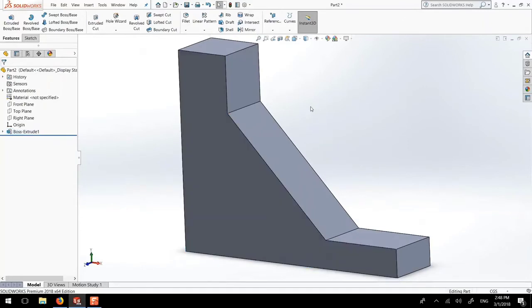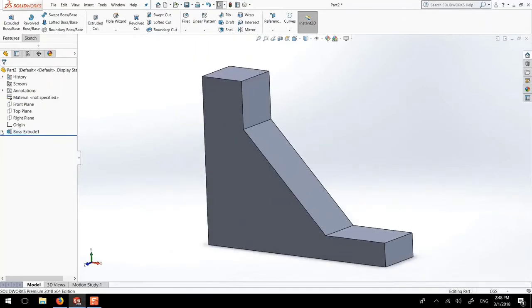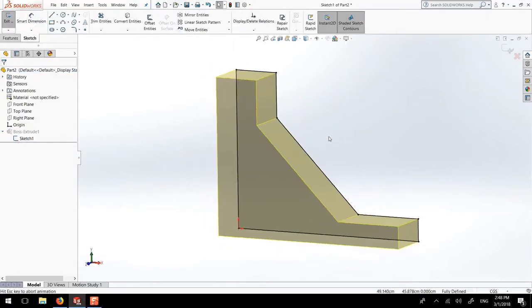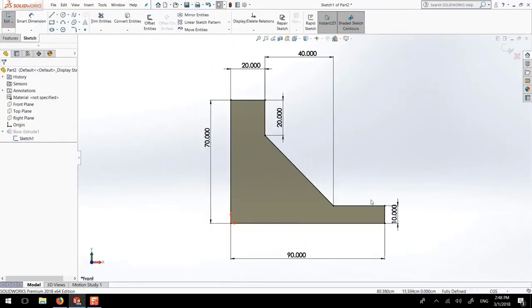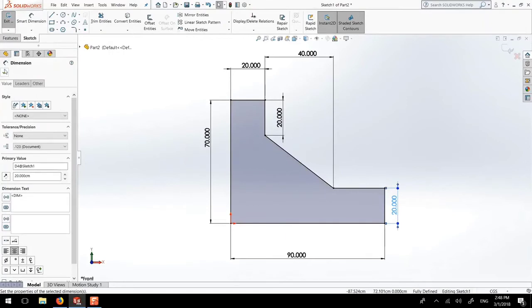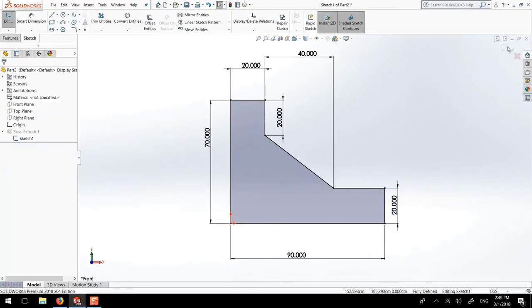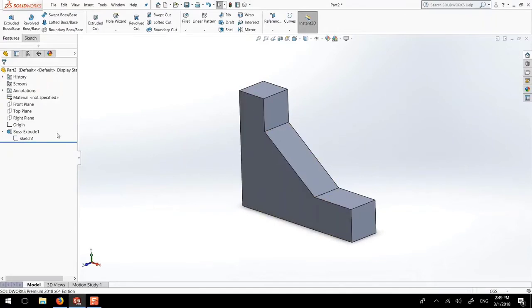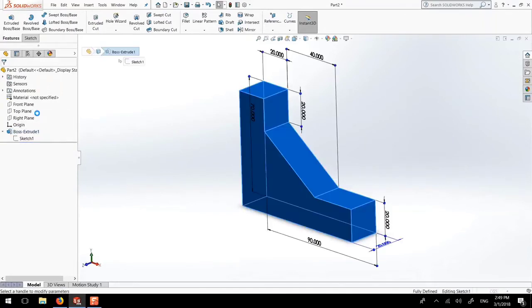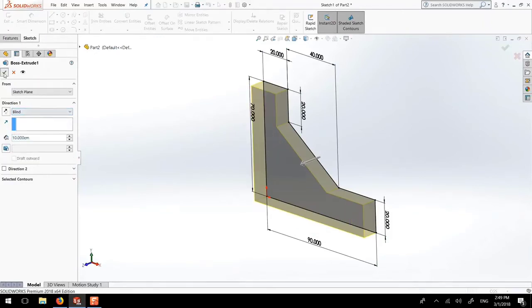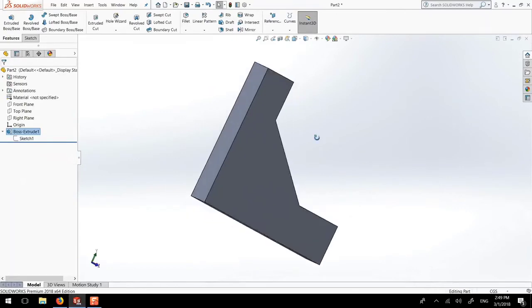And if I want to do any change, the drawing is here. So I can go edit sketch, maybe Control 8. And maybe I change my mind. I want this to be 20 now. So I could type 20. And if you exit the sketch here, we're back at 3D. If I want the depth now to be thinner, I can go 10. Voila, I hope this is useful.